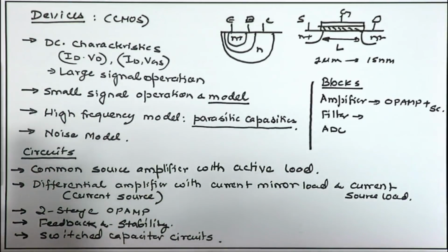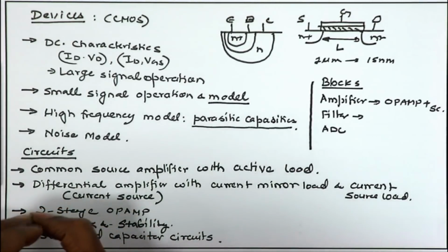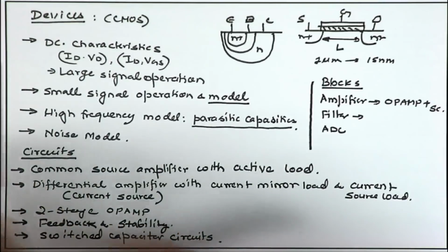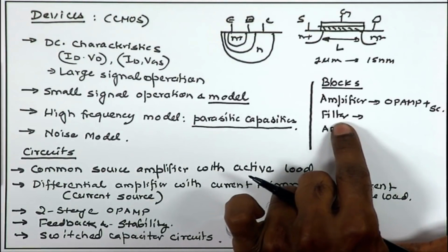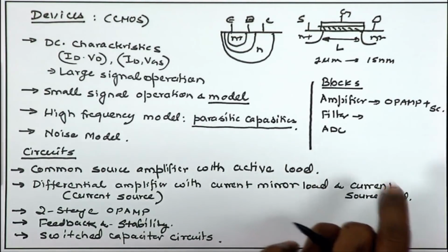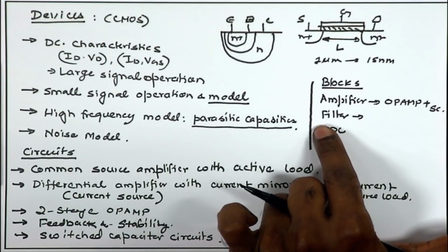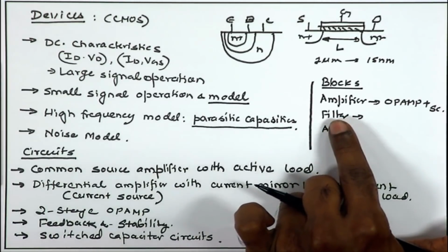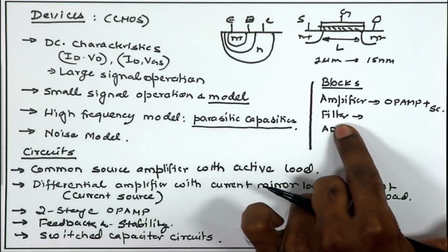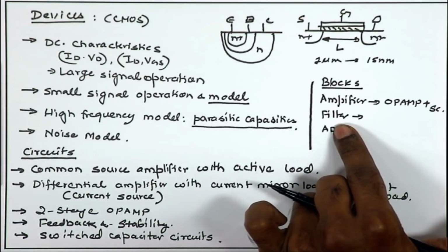Likewise for resistors also, we need to take care of the practical constraints provided by the IC design environment, and appropriately choose the R and C components to meet our filter characteristics. Many other issues like component variations and mismatches are going to play an important role, and it is necessary to consider those while trying to arrive at the desired frequency characteristics of the filter, and that tells us about the kind of topology we are going to require to meet our specifications. A simple op-amp with R and C feedback may not be the best topology to use because we do not have those R and C values available.